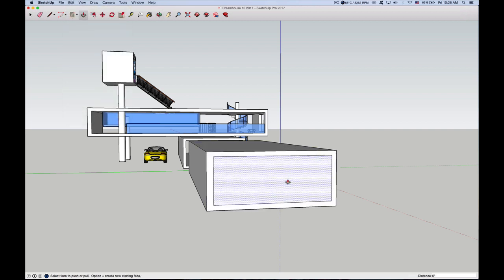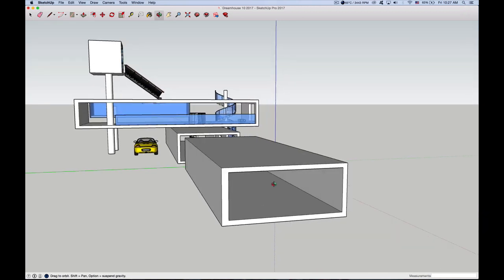You highlight this part instead of this, and then you keep pushing in. And now at the end, you can see that it turns blue, and when you see this blue dotted line, it means that it snapped on the other side of the face, and then it will open up, right? So I can see the other side.